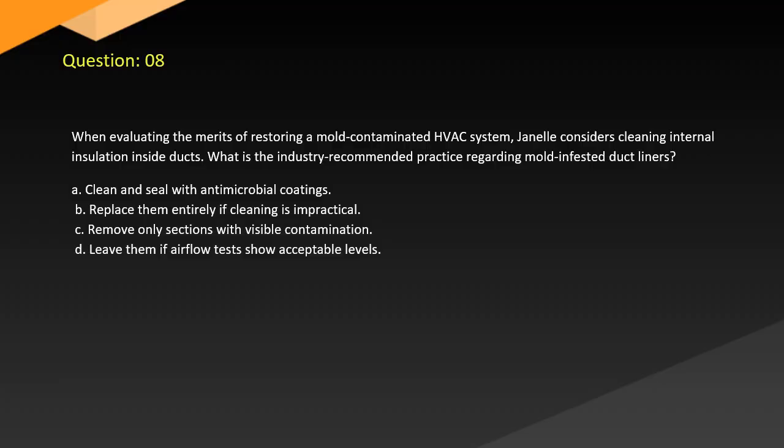Question 8. When evaluating the merits of restoring a mold-contaminated HVAC system, Jenna considers cleaning internal insulation inside ducts. What is the industry-recommended practice regarding mold-infested duct liners? A. Clean and seal with antimicrobial coatings. B. Replace them entirely if cleaning is impractical. C. Remove only sections with visible contamination. D. Leave them if airflow tests show acceptable levels.